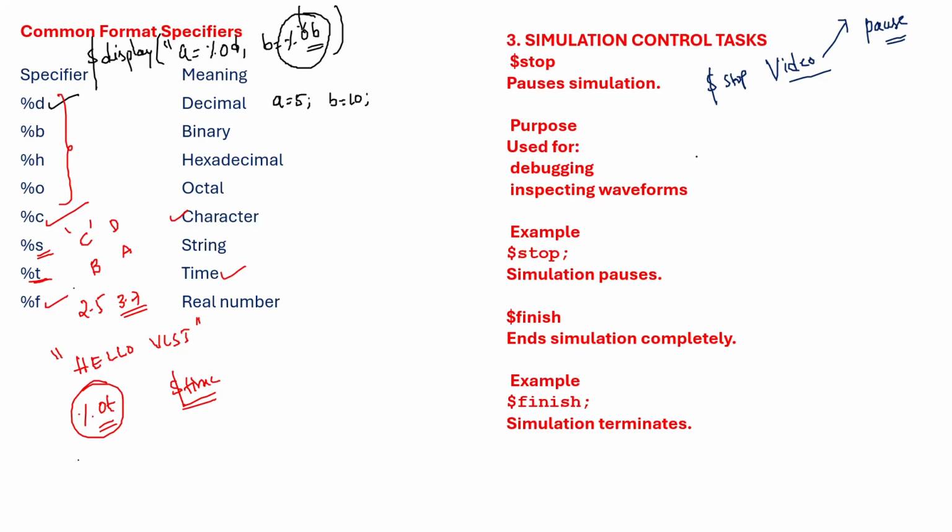Otherwise, $finish we are utilizing means it terminates and ends the simulation completely. There is no stopping, just ending the simulation. With the video, if you want to resume from that position you can, but here it is not like that.